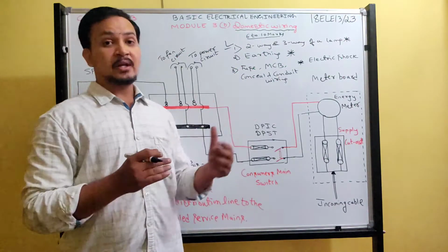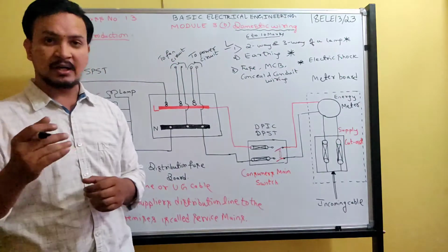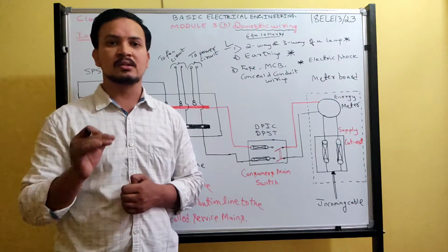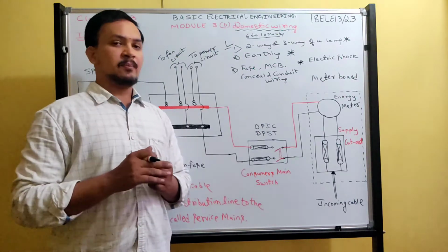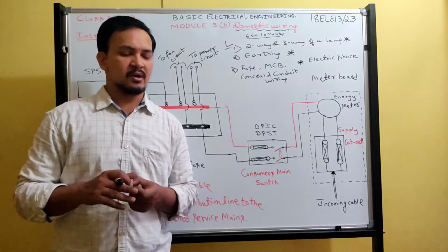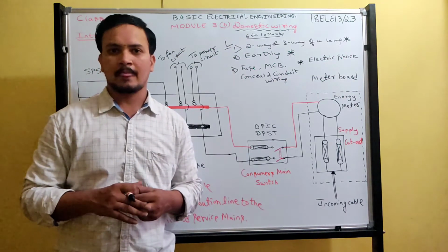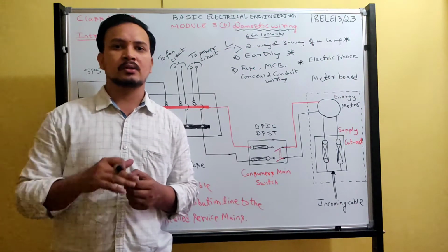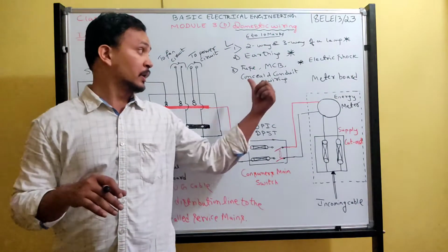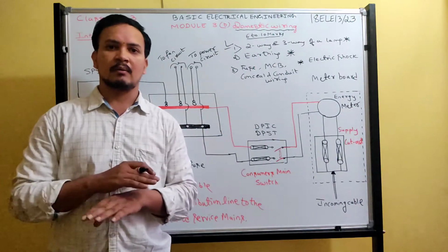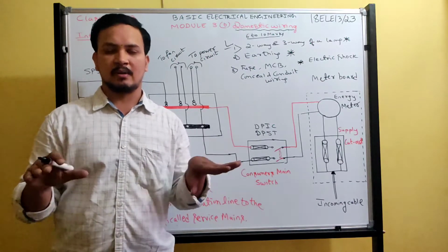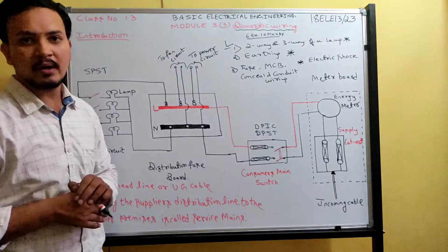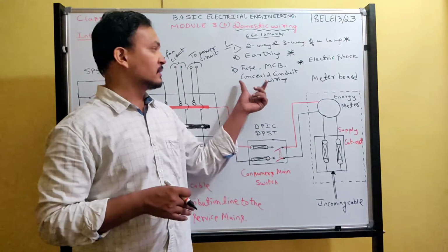Coming to types of wiring, we have so many types, around 5 to 10, but the syllabus concentrates on concealed conduit wiring, because if any building work is going on, the majority of the wiring will be concealed conduit wiring. When roof construction is going on, before putting cement on the roof, they make the conduit wiring. Once everything is done, they seal the entire conduit wiring with cement. So it is called concealed, completely closed. You cannot see the wiring. The syllabus asks you to study more regarding this.